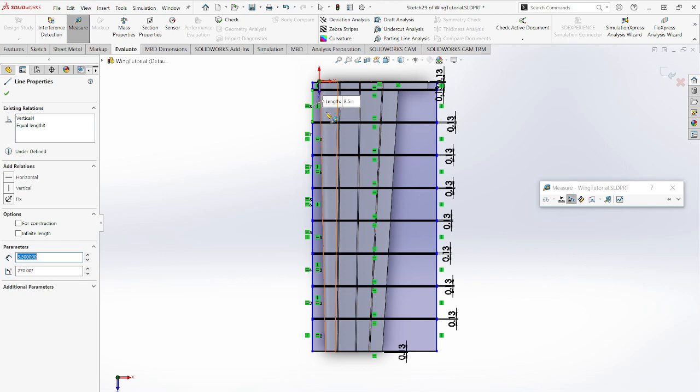And so what we would do is we would set each of these ribs, except for the outermost one, as being equal to one another. And then you would manipulate that equal dimension, and this outer one would change to just fill the little gap out there. And you would set them to something that you're able to dial in with, say, a pair of calipers.